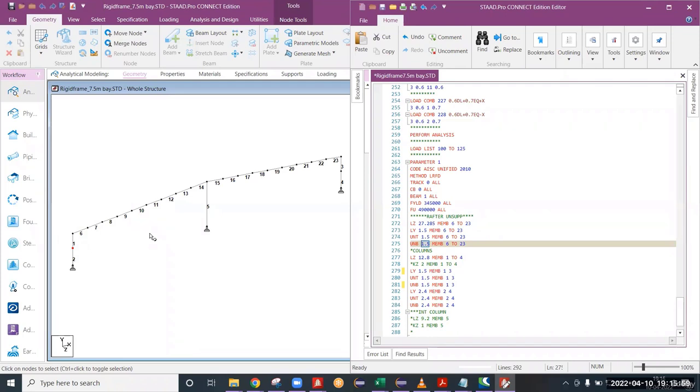I have discussed this in the last class. There will be a channel. Flange brace means a channel or a plate, a thin plate. That is a flange brace that will be provided from every purlin to the rafter, diagonally, if you see.